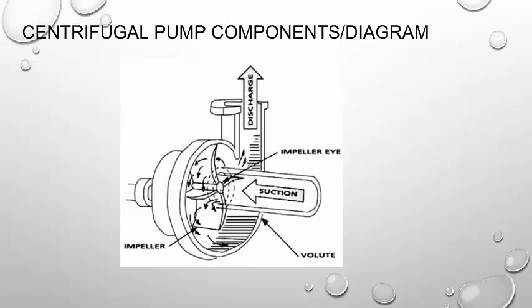So as soon as I create that pocket, the water coming from the suction end will go to fill it. And as things continue to move around, they will move away from the impeller, right? So it uses this idea of centrifugal force to move that away. It's actually quite brilliant the way this thing works. It's not the only thing, though, that is happening inside this pump. Okay. All right. So make sure you understand these things. This will more than likely show up on your quiz. All right. So components of a pump: suction end, discharge end, impeller, impeller eye, and the volute. Make sure you understand what each of these things are and be able to label them.